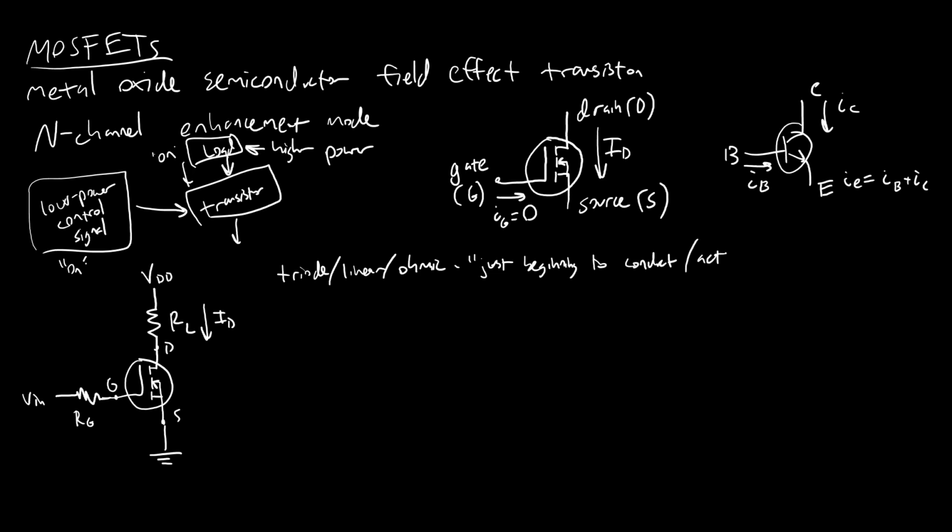Or acts like a variable resistor, depending on which textbook you look in. And here, I'll put quotes there and parentheses there, whatever. This is once the gate to source voltage, VGS, has started to exceed the gate source threshold voltage. So you'll see this in the MOSFET datasheet. VGS,TH: for this to start conducting, we need to exceed a threshold voltage there.